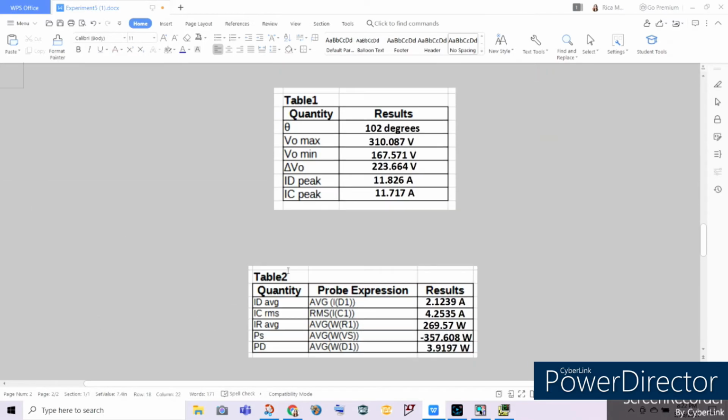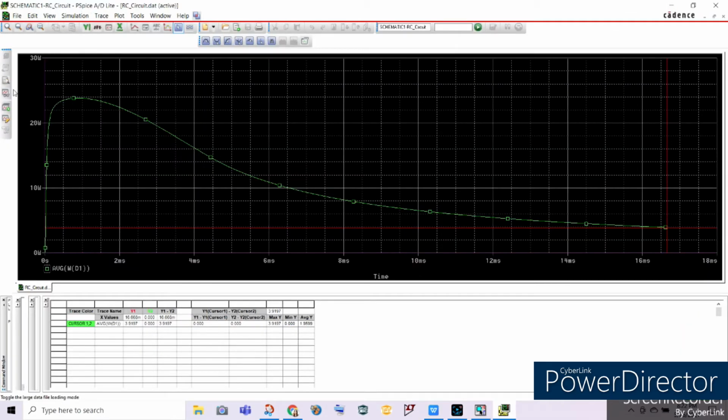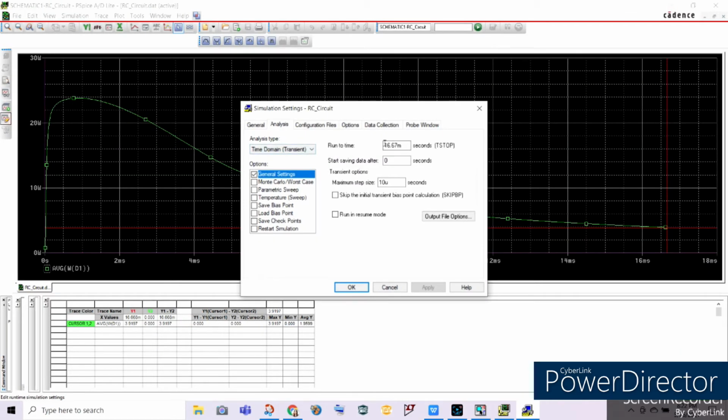And if you notice, our values of current as well as voltages here are quite large, as we expected, because we only restricted the data to the first period of our output waveforms. But if we will be considering the steady state results of this waveform, we can edit the simulation, considering a 50 milliseconds runtime.